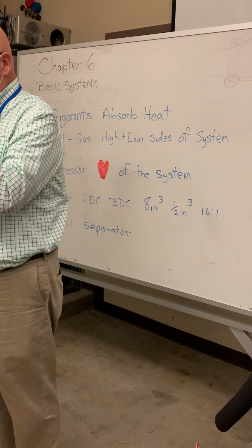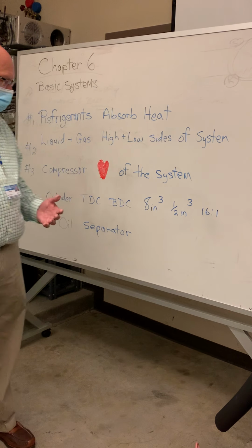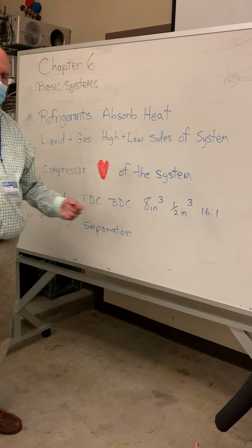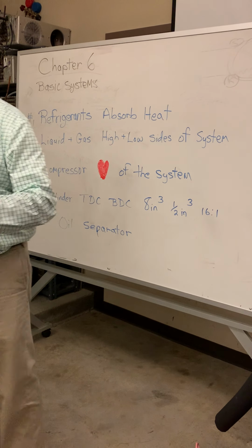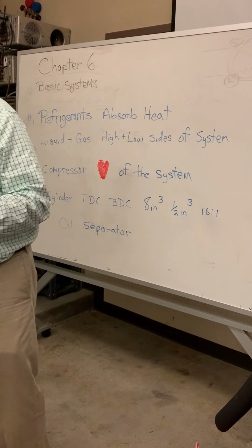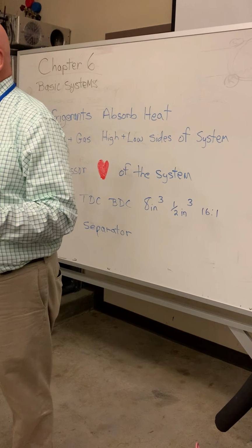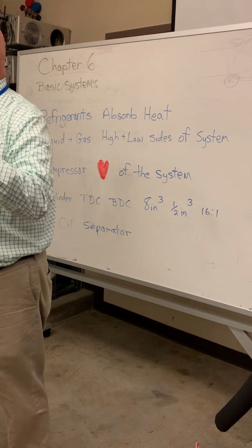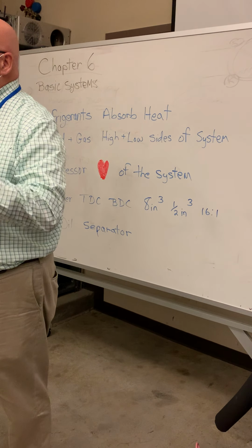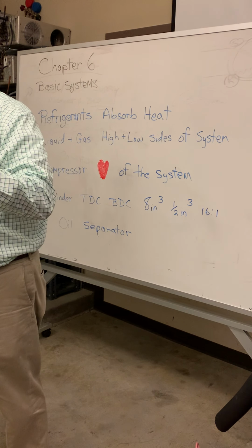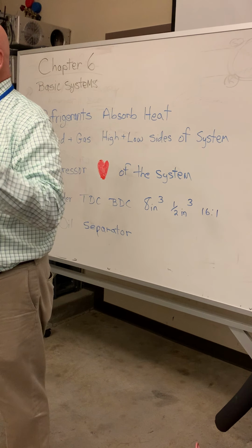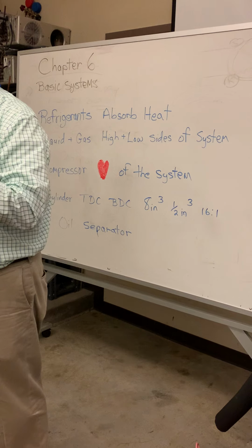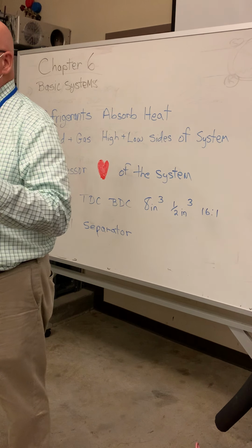Matter of fact, it looks exactly like that. You're going to see terms like top dead center, bottom dead center, that are definite references you would have with pistons and things like that. So instead of intake and discharge piston valves, we have reed valves.